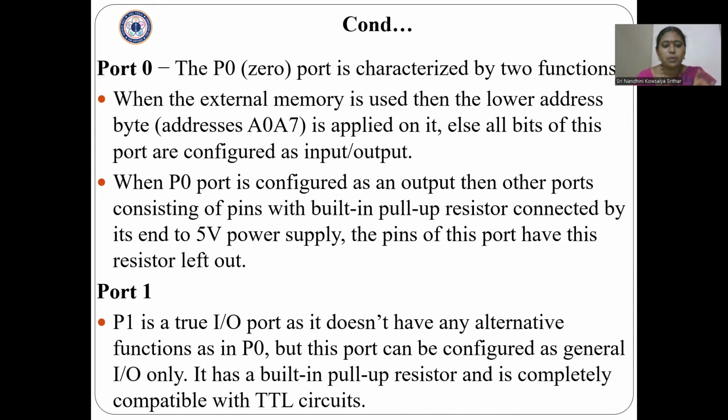Then port 1. Port 1 is a true input and output port. It does not have any alternate function as in port 0. It has built-in pull-up resistor and it is completely compatible with TTL circuits.